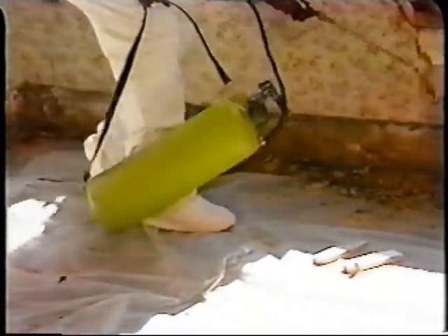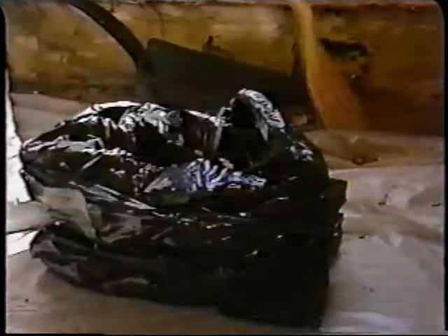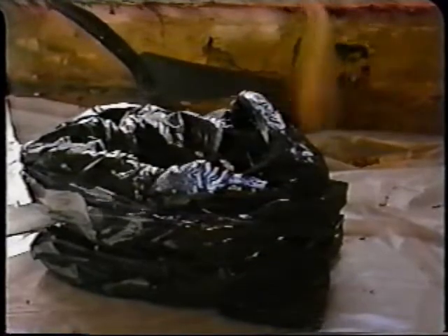This debris is first wrapped in 6mm plastic, then sealed. Smaller, sweepable debris should also be removed on a daily basis. Before sweeping, lightly spray the area with water to keep the dust down. The swept debris is double-bagged and sealed. All materials should typically be tested to determine if they are hazardous waste in order to arrange appropriate transport and disposal. Chapter 10 of the HUD Guidelines offers additional advice on waste disposal.